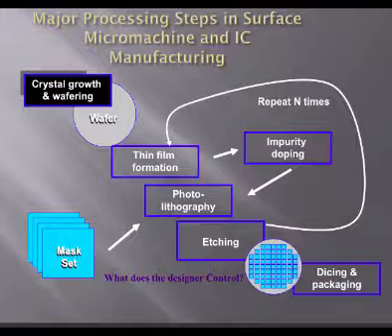So the photolithography guy knows the difference between mask and printing, and he knows also, because he talks to the etch people, the difference between lithography and etch. And he goes, okay, I got to add 0.2. So then everything that's a micron on the mask for that layer is going to be 1.2 micron drawn on the mask because he's losing 2/10 in the process.